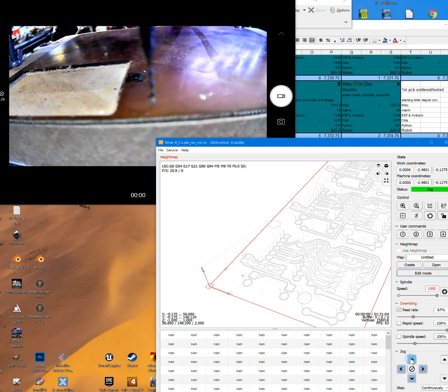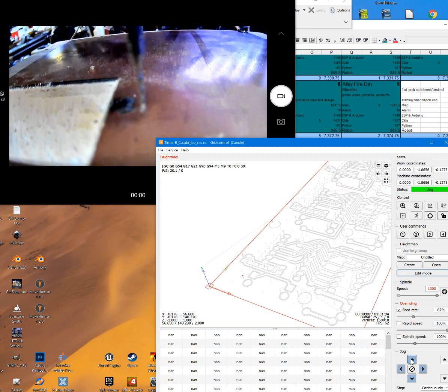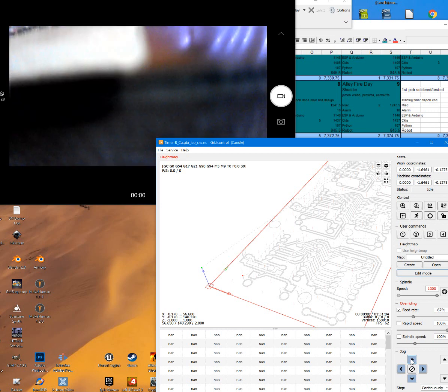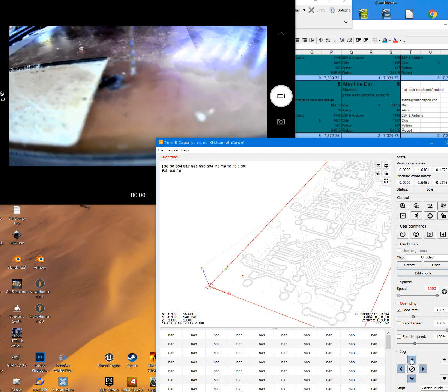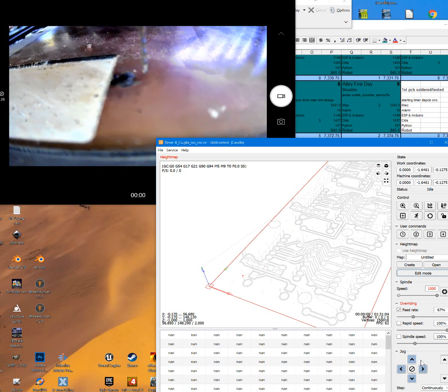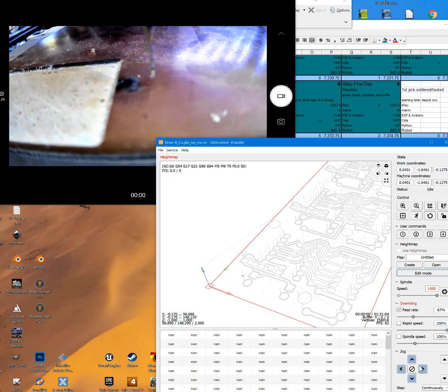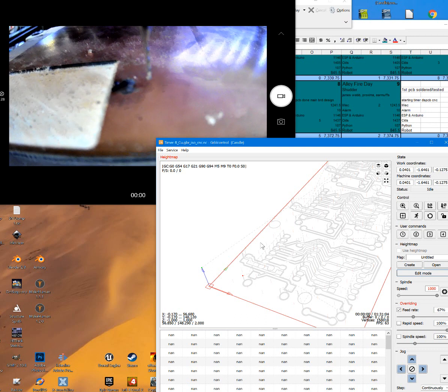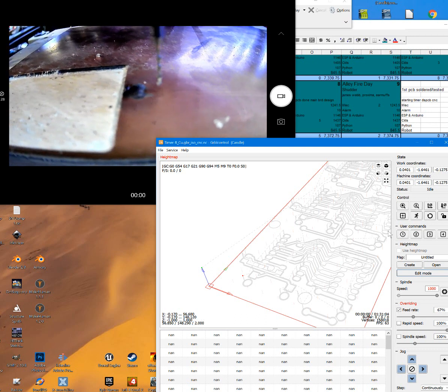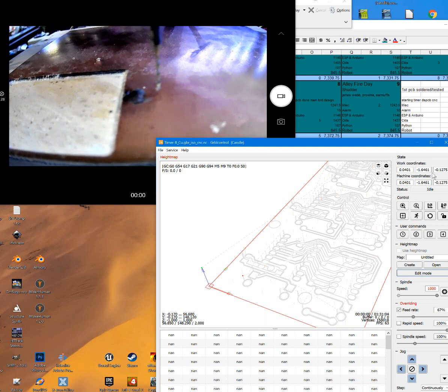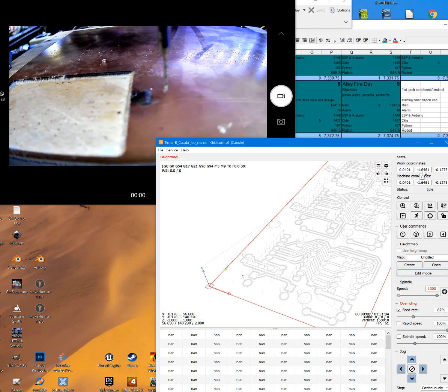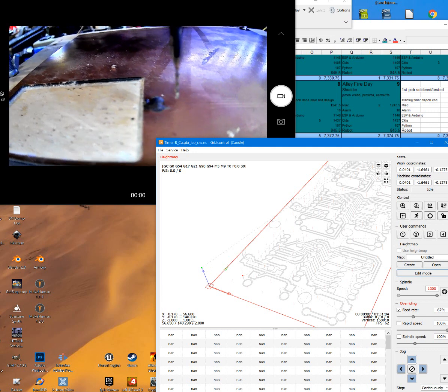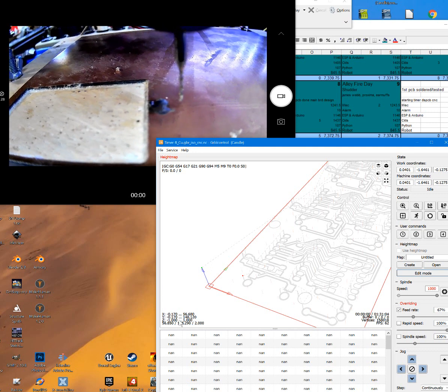But what I like to try to do is get its home as close as possible. But see right there, our router bit will end up going through it, so I'd like to move it over a little bit. And understand this, even though I've got the machine coordinates set to read out in mils, inches, this stuff over here is still in millimeters.